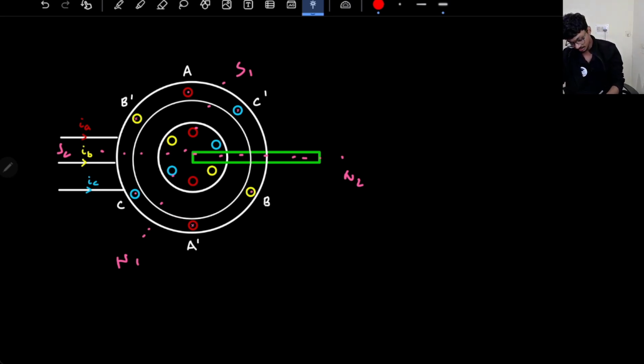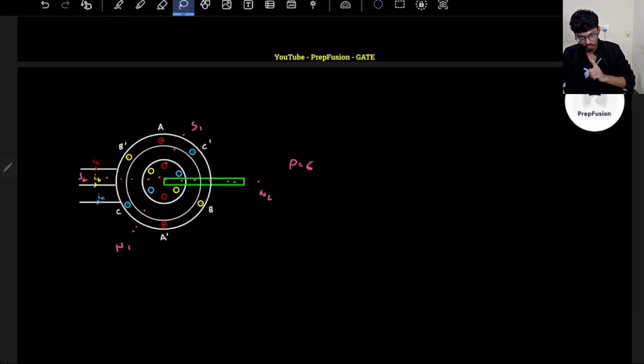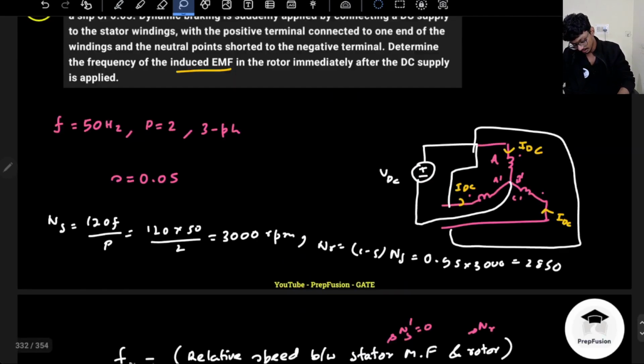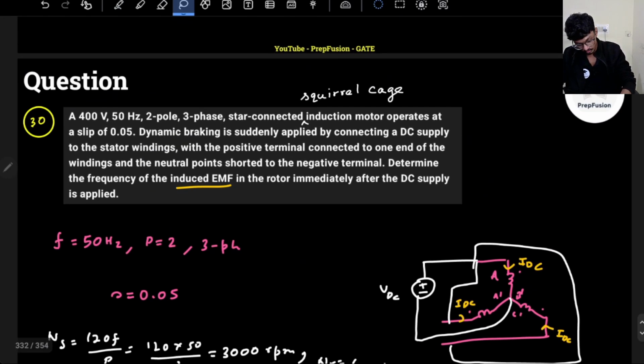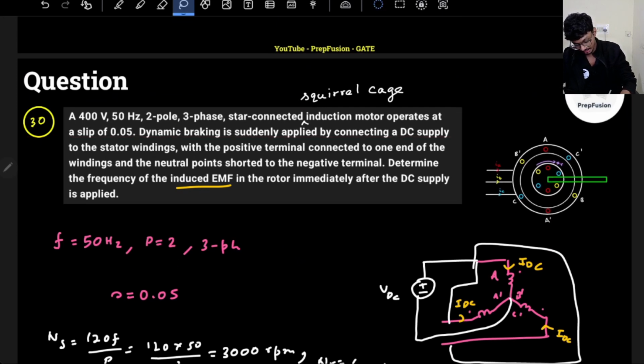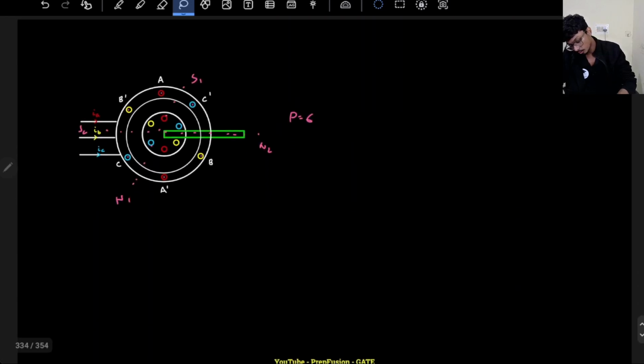You will observe that each of the adjacent windings is creating a pole. So the number of poles in this case becomes 6. Just have to be careful. Actually it would have been better if they had provided the diagram as well. The question would have been more accurate if the diagram was provided. If the diagram is not provided, then the question becomes kind of irrelevant. So the winding diagram should also be provided. That was a mistake on my behalf. So now the pole becomes 6.